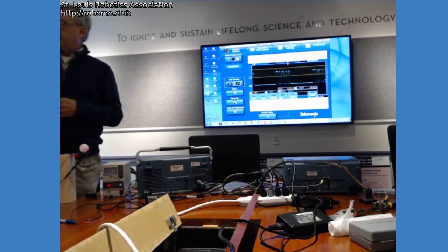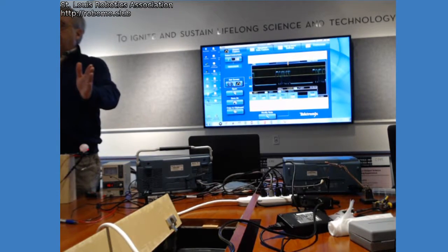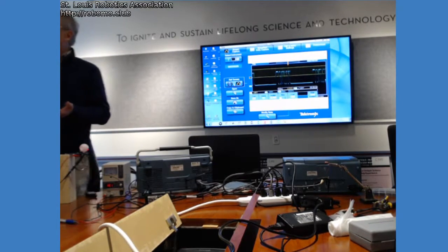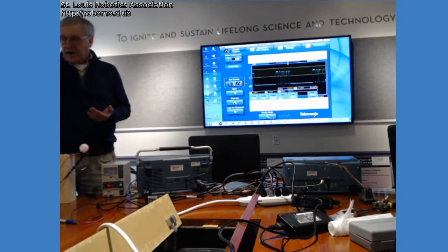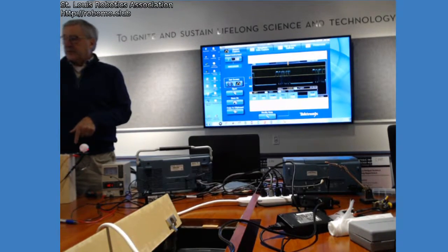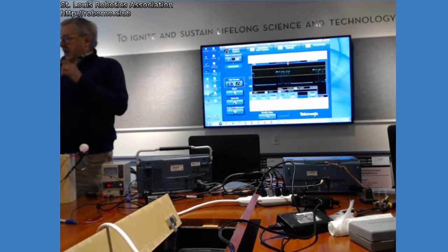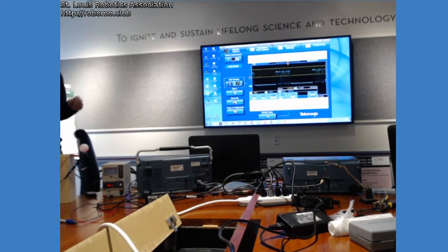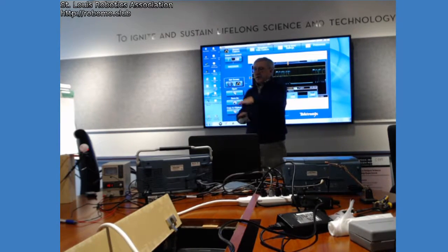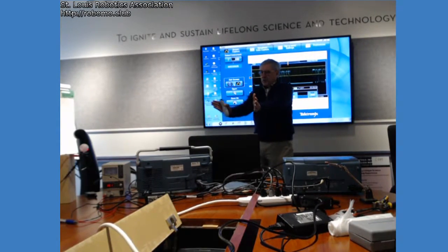Whereas this guy is an LED, and he spreads out. You can tell that when you're at home, when you turn on your TV, you don't have to be directing it right at the TV. You can have it over here and it'll still do a pretty good job of turning that TV on. And that one's actually a really strong signal. But the problem is that the farther you get away, the more it's going to go down, because it's putting out that light into this solid cone, the solid angle, and so the more you spread out, it's increasing this way, it's increasing this way.